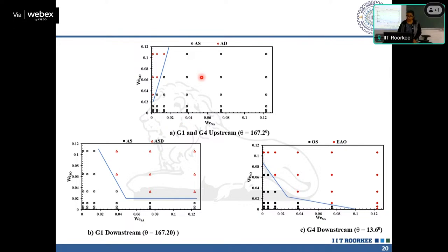So if it remains that way, the only thing that changes is a sudden change in area. What will happen is that we have slug and droplet formation enhancement, and that's all. When we have a change of wettability combined with the change of area, what happens? We get an entirely different set of flow regimes. So here we have aqueous slug and aqueous drop.